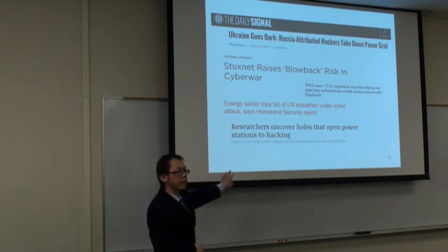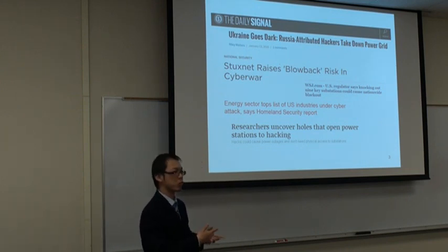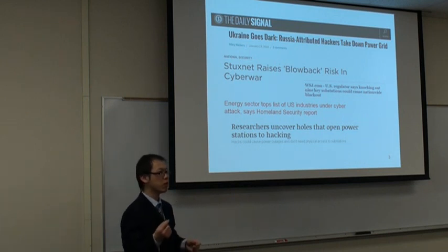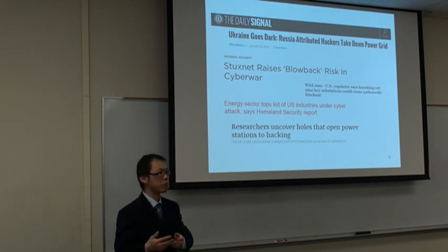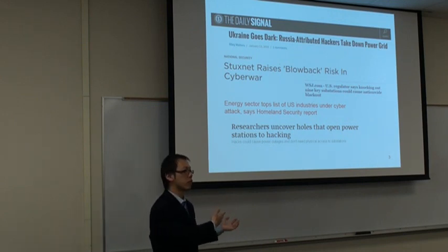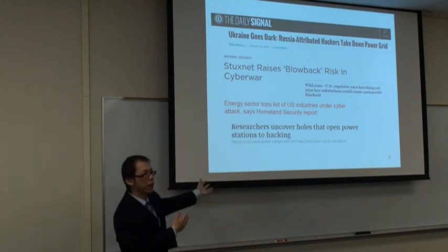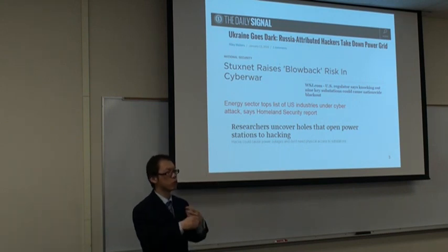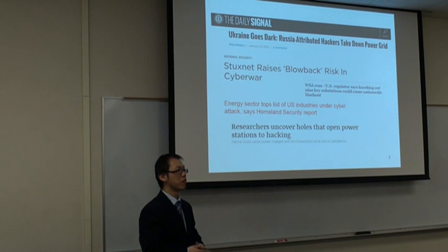In my evaluation, the time to generate a decoy measurement usually is just 1/5, or 20%, of the time to perform the normal state estimation. If there's any speed up mechanism that can speed up the normal state estimation, because you cannot expect the state estimation, which is performed periodically, to take hours, even in a normal power system. So if there's a way for the power system to speed up the state estimation, that way can also be applied to generate a decoy measurement. That's one way of solving the scalability problem. But I still agree with you, that will not be enough for the PMU measurement.